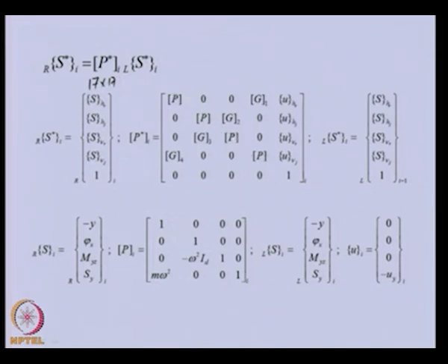This is the P matrix which we have already obtained earlier without gyroscopic couple. If we refer back to previous lectures, we had these diagonal terms, and all other off diagonal terms were 0 earlier, except these, which are because of the unbalance.